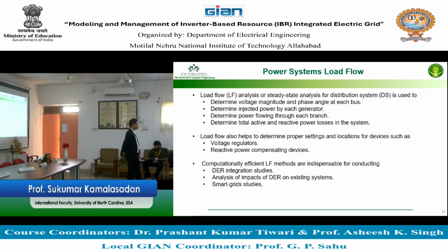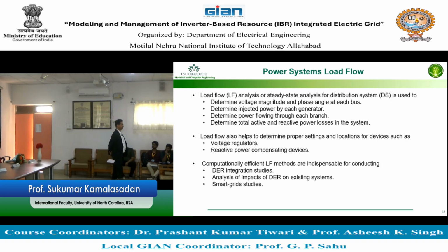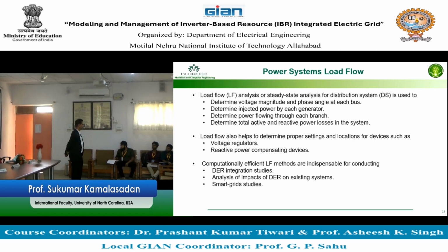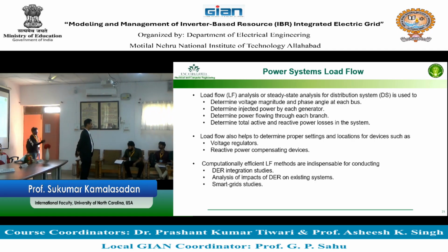You can get the difference between the source and the load, to see whether the source is sufficient to supply the load. Yes, that's one objective. What else? Why do you want to run a load flow? Angular displacement of what? One of the main objectives of the load flow is to get the voltage magnitude and angle of an electric grid. So the next question: why do you care? Why do you want the voltage magnitude and angle?